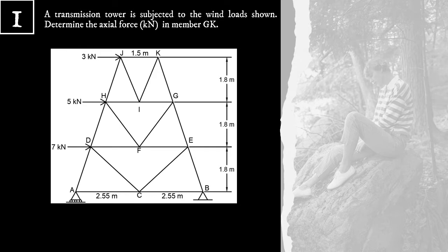We can recall that for a non-concurrent force system, there are three equilibrium conditions, namely summation Fx equal to 0, summation Fy equal to 0, and summation moment equal to 0. Three equations, three unknown forces. Therefore, the maximum number of unknown forces in a section should be equal to 3, ideally.